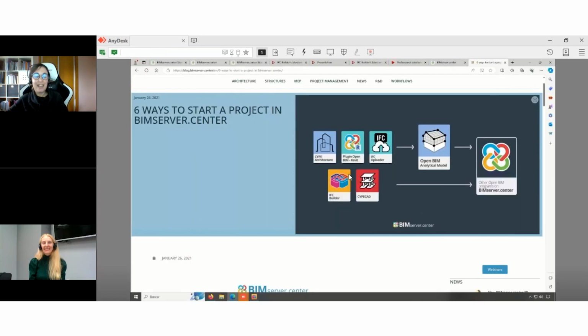The difference between them is that IFC Builder produces an IFC that is an analytical model. This means that this file can be read automatically by energy analysis software or acoustic analysis software. It has directly the edges, surfaces, and everything, and adjacencies. So it's more direct. That's great.